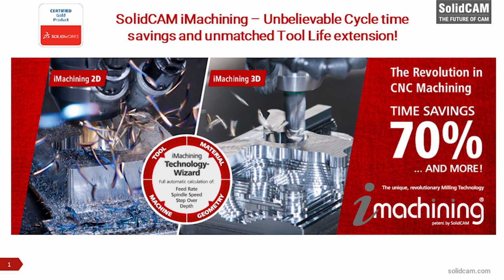Remember that iMachining is taking into account the machine kinematics. So when you set up your machine definition, if you set that up correctly, then yes, if you switch machines, you simply recalculate the iMachining toolpath, and the iMachining wizard will take that new data into account, and it will reestablish that set of parameters for first part success.